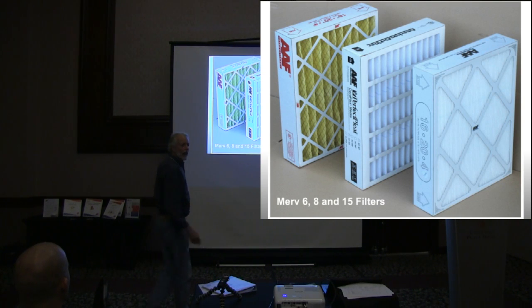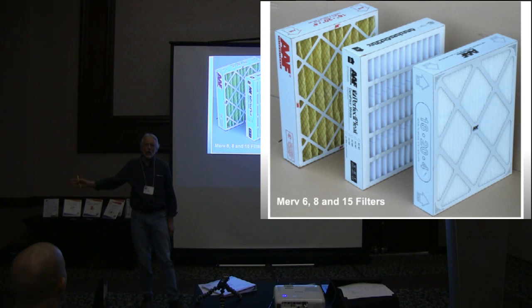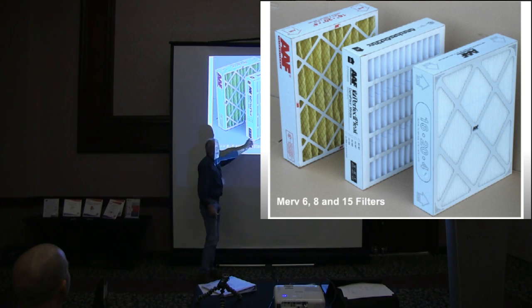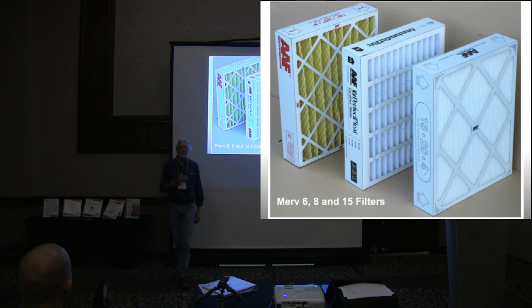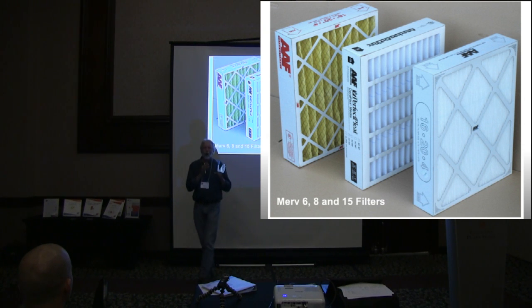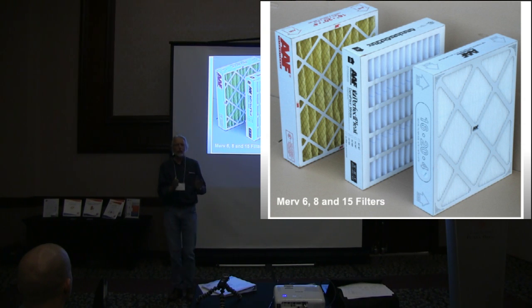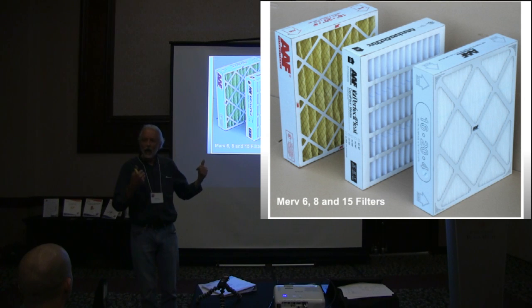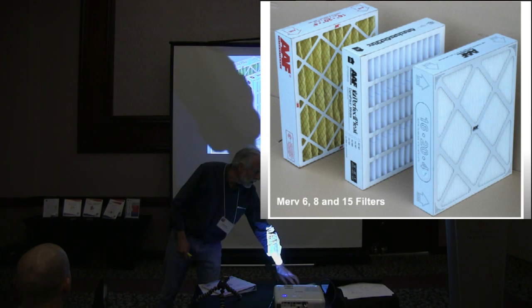Why do we make an issue of that? Because the new appliances move a hell of a lot more air than the old ones, especially if you go heat pumps. Number 2, people are starting to demand better filters. And if you start demanding better filters, you're going to have a higher degree of static pressure drop in order to get the filtering performance the public wants. So you can't put this kind of stuff into a standard system because you have gobbled up all your available static pressure from your plants, consumed in overcoming a bad duct system, so you get nothing left over for the benefit of cooling coils or proper filtration.